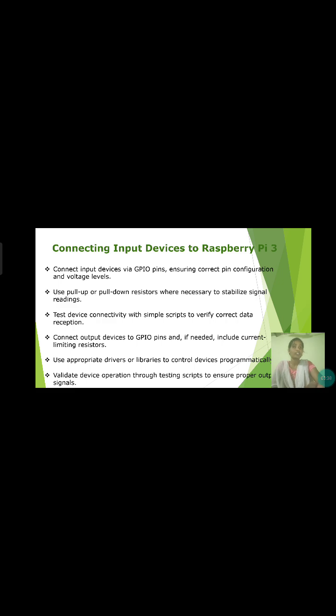Output devices are also connected through GPIO pins. We use current limiting resistors to protect components. Sometimes drivers are required for devices like motors. Finally, we test the output using programs.